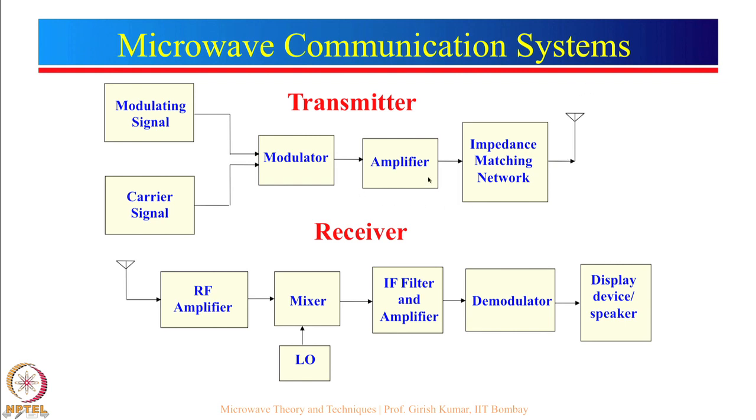Now, for a high power solid state amplifier, the output impedance may be of the order of a few ohms, even 2 or 3 ohm. If you connect 2 ohm with the 50 ohm, the voltage ratio 50 divided by 52 will still give a good voltage, but the problem is that the current going through will be very small, so the net power will not be very good.